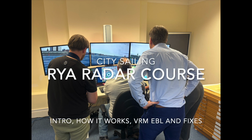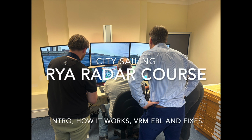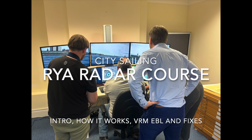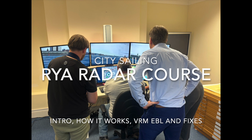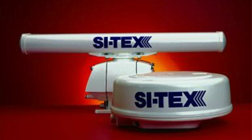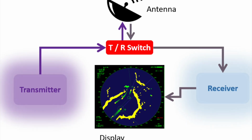Radar. What is radar? Well, the term radar is an acronym meaning radio detection and ranging. It's a device which measures the time it takes for a pulse signal to be reflected from an object. The radar consists of a transmitter, which is the part that turns around on top. On your yacht, it will be contained in a box. It also consists of the screen that you see on the boat, and it has a TR switch which switches between the transmit and receive.